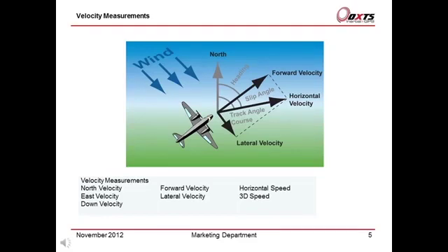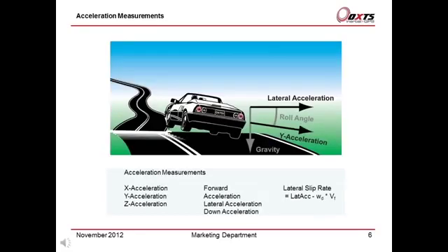The heading of the car is not the same as the angle of the velocity vector. To measure the track angle, you will need to measure the heading minus the tracking angle, which will equal the slip angle. The underlying calculation in the RT integrates the accelerations to give north, east and down velocities.